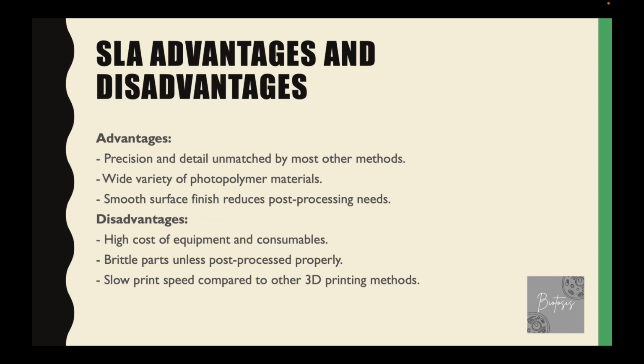You can also tell me about the case studies, more and more case studies where we can use SLA printers. Now, advantages can be precision and detail, unmatched by most of the other methods, a wide variety of photopolymer materials, and a smooth surface finish, which reduces post processing needs, right?